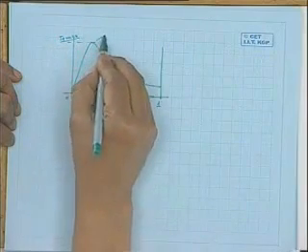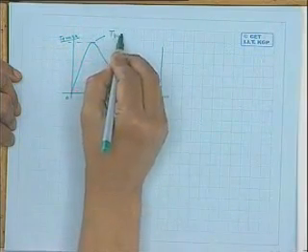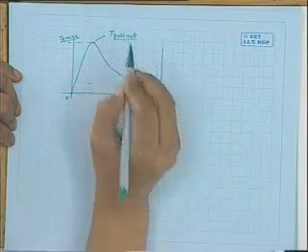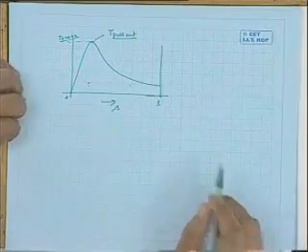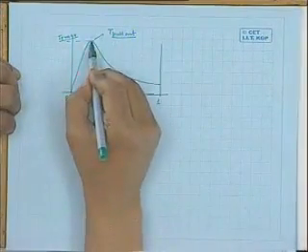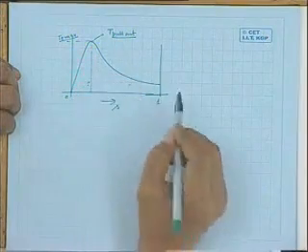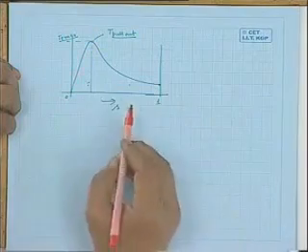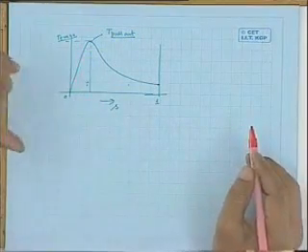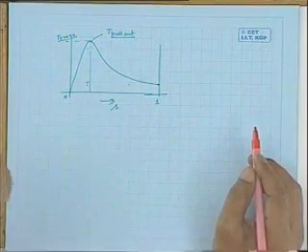This is slip. This is Te max. So this Te max is sometimes called T pull out also, pull out torque, because the machine cannot develop a torque greater than this. The machine will be unstable beyond this. So this is the starting torque.